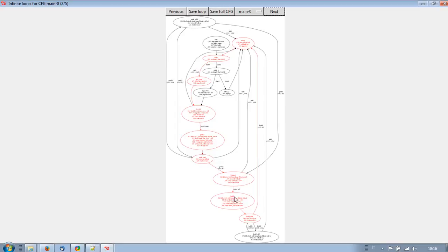And after this period has passed, if the input is still active, then this cycle is re-entered and the output is activated again. So this is a dangerous condition because it depends on a fixed level on the input. It would be better if it depended on a continuous check of the correctness of operation of the microcontroller. The same applies for the third cycle, where simply the input that is checked is the second input.